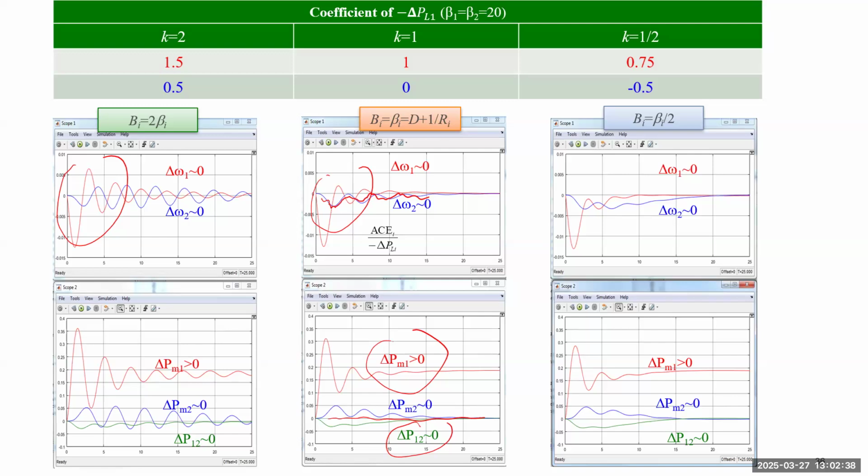When k is 0.5, what's interesting is the second unit simply doesn't want to do any active control, and you see this curve will basically just stay under the nominal frequency. It even increases the deviation of the frequency, but eventually, after taking a longer time, the system still goes back to roughly the original frequency. Even if it may not be, because this is AGC, eventually we'll go back to 60 Hertz.